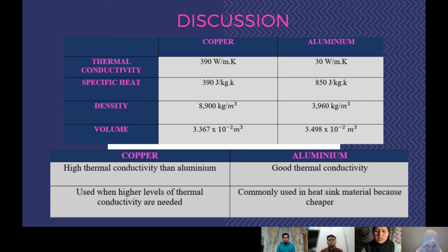With a temperature gradient in a body, heat will transfer from the higher temperature region to the lower temperature region by conduction. As you can see, copper has around twice the thermal conductivity of aluminium, but copper is 3 times as dense and more expensive than aluminium. But we can say that copper is less ductile than aluminium, so it cannot be extruded into a heat sink.